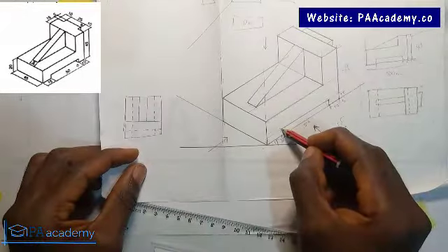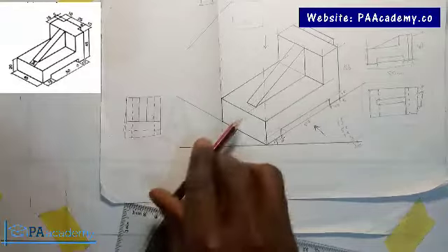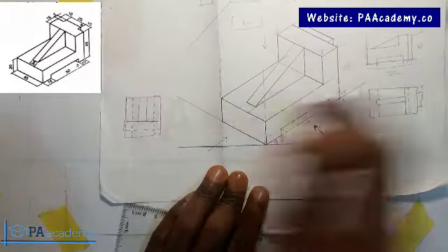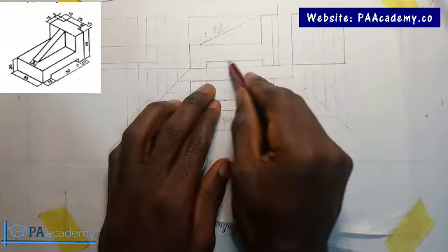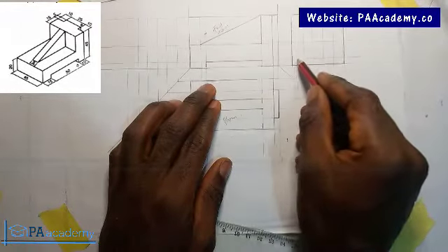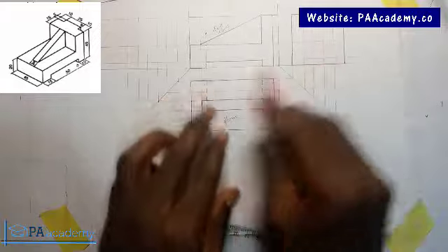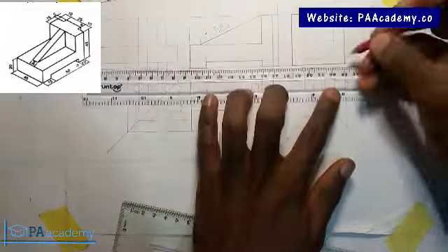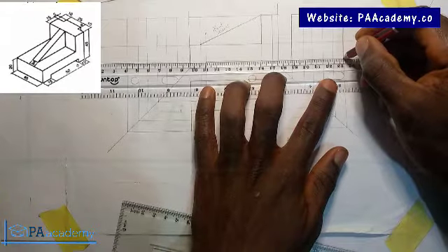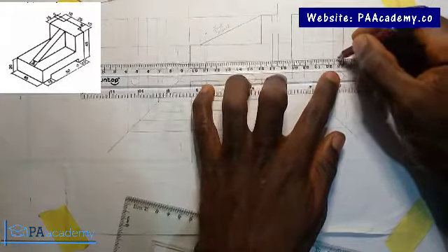this part here. Like if you are looking at it from here, you can't see it. That's why you have short dashes. Now the line that represents that, if you look at it, this is it. This is the line here. So that's why I'm saying that all of those projections, when you are working with the side view, they are already there. So let's just use it. This is it here. So it's going to be short dashes.